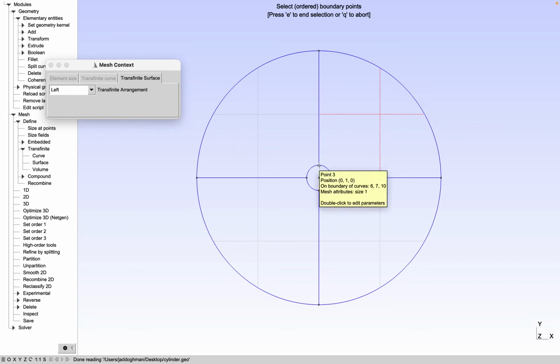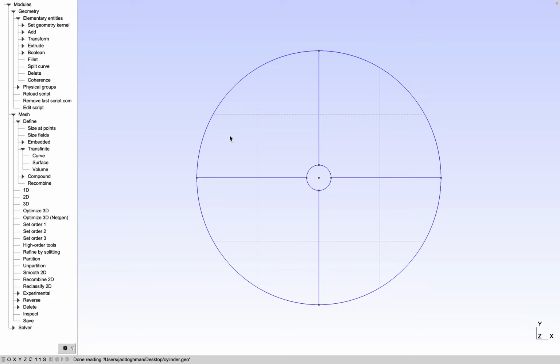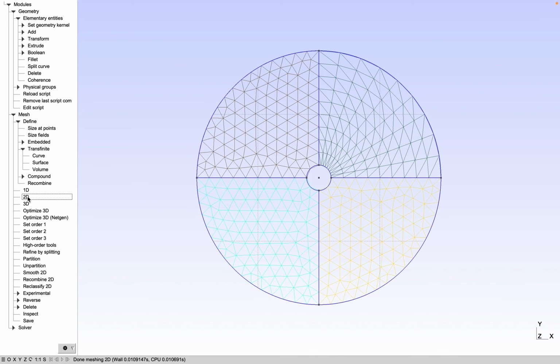This means that I can create the first point here, select the first one, the second one, the third one, and the fourth one, and then hit E, then Q. This one here, in this case, it changed entirely the mesh type. We can hit on 2D and it's apparent. But since I need to be structured, I need to get rid of these diagonals of each rectangle.